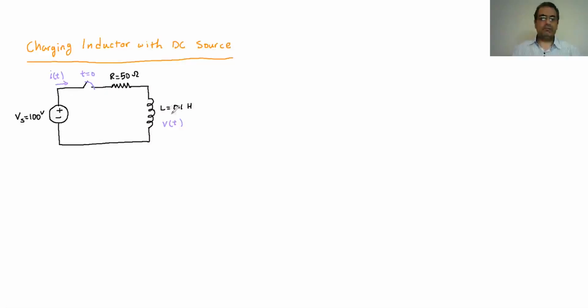So it gets to a steady state condition, in which case it behaves as if we have only a single source and a single resistor. It behaves like it's not there; we can just replace it with a single wire. So we want to see what's happening between the time we close it and the time that it becomes steady state.